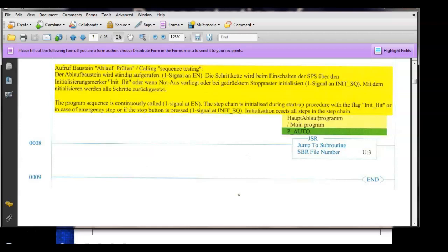If you went into the robot, they're all unconditional. If you looked at the main routine on that robot, it's jump subroutine, jump subroutine, jump subroutine, pick up block, jump subroutine. So the main program is nothing but a bunch of subroutines. They've assigned each act the robot does, like pick up a spring, to a subroutine.